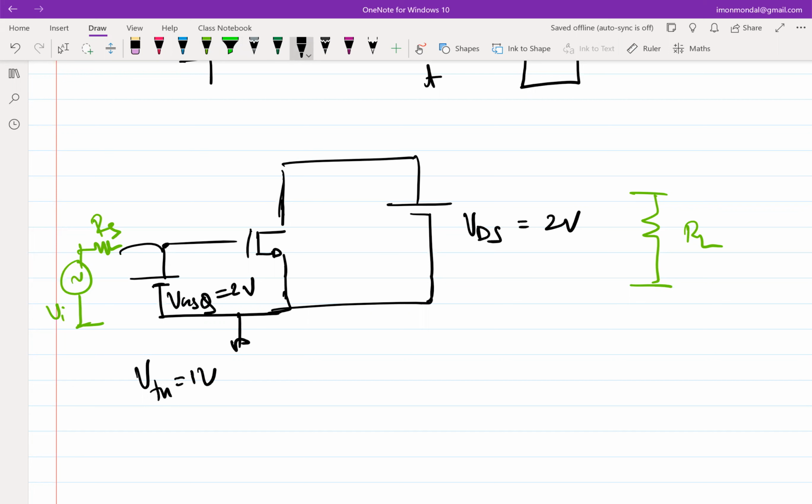What is the issue? Backflow. What do you mean by backflow of current? Part will get into the RF. Okay, I agree with what you were saying, but is there an even greater concern? I am expecting the incremental voltage VI that I'm applying should appear fully across the gate and source.